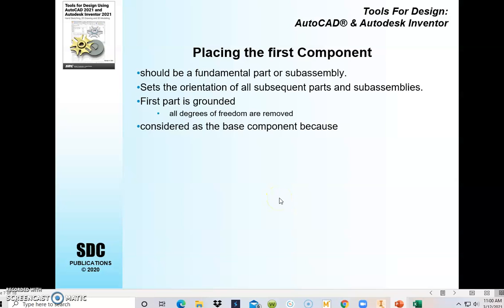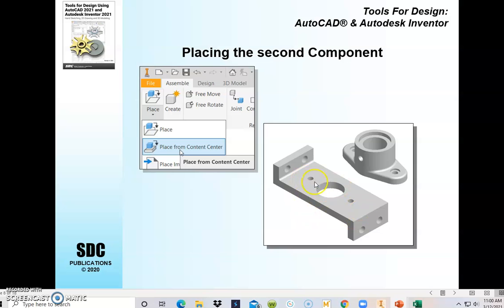And then you'll have to start an assembly, which is a separate type of file, and you'll add each one of the parts one at a time, and then you'll constrain them and how they move relative to each other. The base part needs to be the base part, the thing you're going to add things to. Then he's going to add another part, and you're going to fix the base to the origin if you follow his instructions. The way I did it, I ended up having to rotate it. If you right click, you can rotate it around different axes to make it look like his picture.